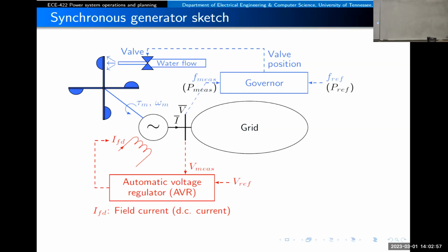You have mentioned this before, that there is a relationship between power balance and frequency, right? Whenever the power balance is perfect, the system will have nominal frequency. But if for some reason you have more generation than load for a transient period, then the frequency might start increasing, right? And the opposite will be true too. If you have less generation than demand, the frequency might decrease.